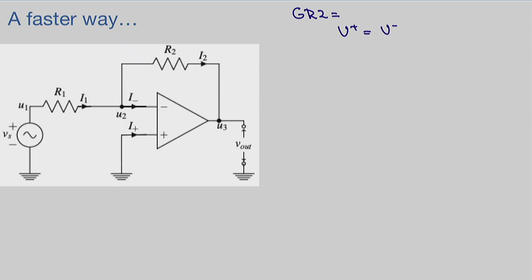Then I look into my system here. I look at the circuit diagram, which was my first question to you, right? Before I did the long way, you knew the answer already. You said u plus equals 0, because u plus was connected to ground. So your intuition is there. Because you know that u plus equals 0, and because we checked and it was a negative feedback, that means that u minus equals u plus equals 0. Okay, that's great.